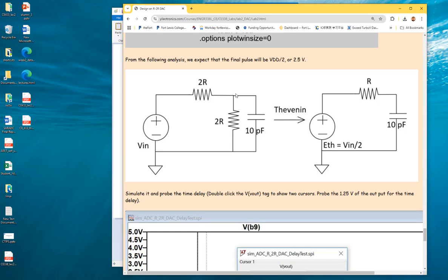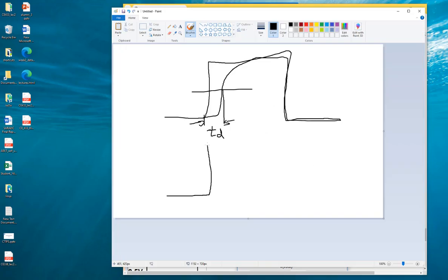This voltage can never reach Vin because of the voltage divider, right? So if we simulate this circuit, what we are getting is this and this, right? Agree with that? So you are looking at 50% of the Thevenin's voltage, which is 50% of this guy here. Okay, you are still using the 50% of the Vin. You are looking at here, right? Which is wrong. So you're looking at 50% of the Thevenin's voltage instead.